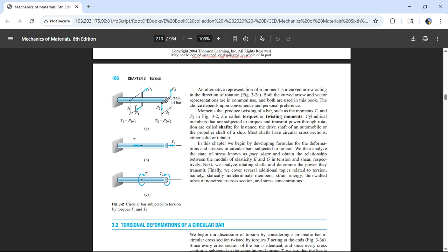And I'm going to take this P1 and pull on that little L shape right there. Well, now what? If I pulled P1 from way over here, is that going to change anything? No, because the line of action of the forces, that's what we're looking at.